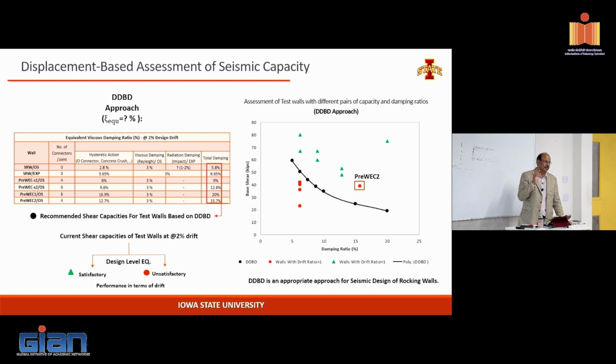That's what the emulation concept went after. If you make the connection weaker, then the connection will open up. If you make the connection stronger, then the member will deform or go through inelastic action. So when you establish this connection at a higher level, they establish the connection to be stronger.